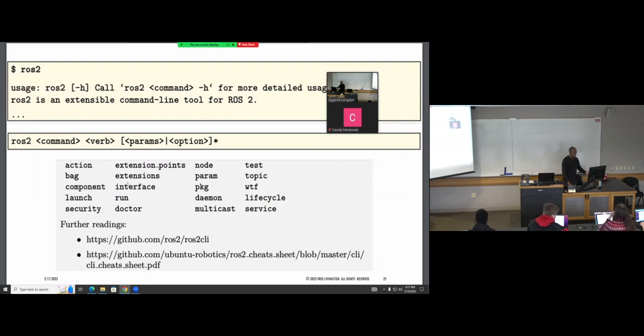So these are just the basic commands that we went over. If you just type ros2 with no arguments, it would give you a list of stuff. Everything tab autocompletes, so if you forget the commands, just type ros2 by itself and it will display the rest of the commands on the screen. We're going to use run, launch, and bag, which are the three most popular things there.